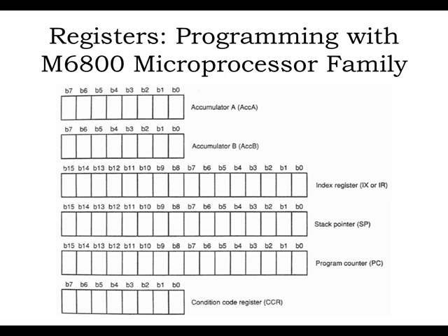Now, these are some basic registers. As I said, we have some registers which are extremely useful. And remember, the registers will vary in sizes and types based on the microprocessor. So these are the list of registers we have for the Motorola 6800 family of microprocessor. Now what registers do we have? Look at this. Accumulator A and accumulator B. Look at their size. They are only 1 byte each. They are extremely useful. They always load some data or do some operation. We'll know about those registers, but at this point, they are the fastest RAM-like memory locations you have inside the microprocessor.